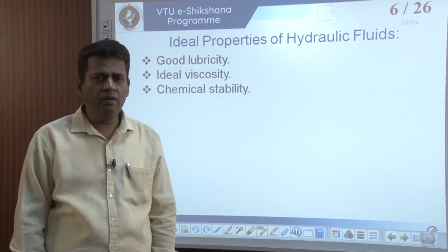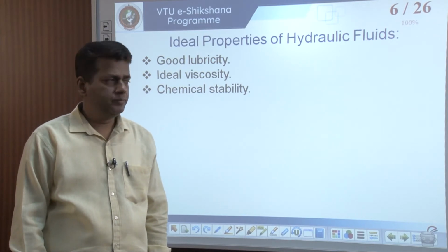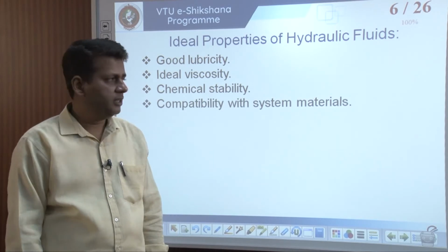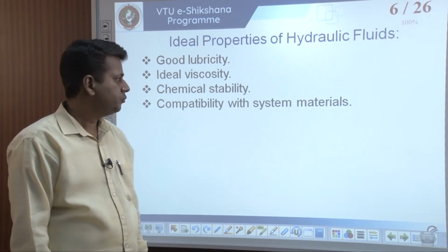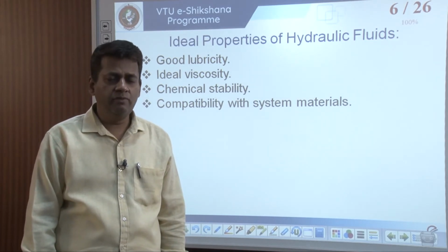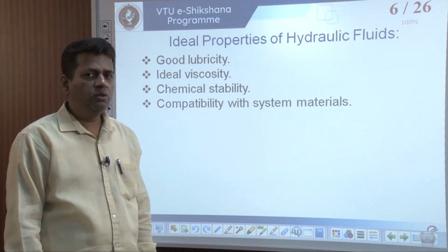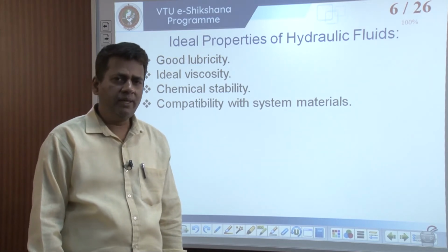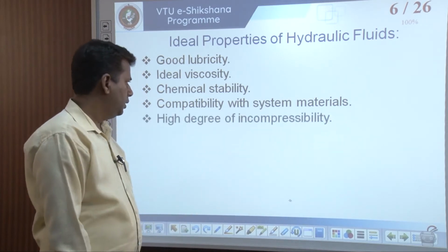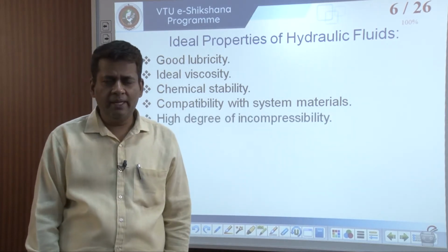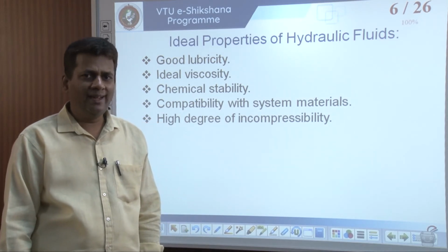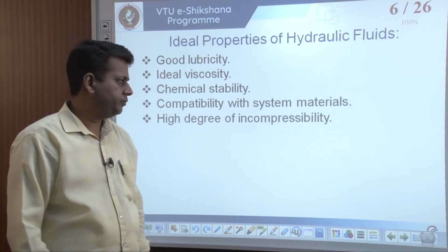So, any hydraulic fluid should be chemically stable and it should not interact with any other members, internal as well as external. Compatibility with system materials. So, compatibility is very important because we need to match the hydraulic fluid for a particular application. High degree of incompressibility, that is, we need to have a hydraulic fluid which has a constant density throughout its operation.